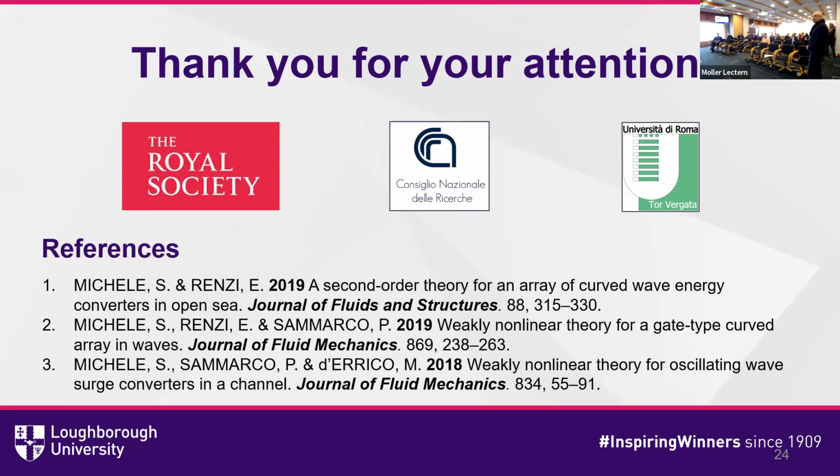Yeah, thank you very much. This is a really good question. The analysis we did is for surface piercing flaps. So we were working mostly with Aquamarine Power, which was a company based in Scotland, and they had a patent for surface piercing flaps. We've also done some analysis for submerged flaps, though only linear, and it looks like already at the linearized order, the power capture is less than surface piercing flaps, essentially because energy decreases exponentially as you move towards the seabed.